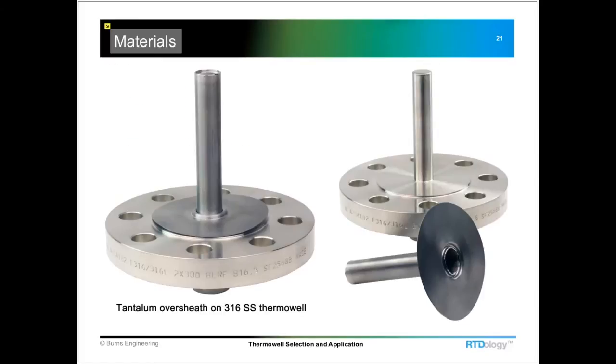One of the more common ways of handling corrosion due to acids is with a tantalum oversheath on a straight stem Thermowell. This is a rather expensive option, but it does work really well. The basic Thermowell can be 316 or 304 or really any other base material that gives you the strength required for that particular application. And then the tantalum oversheath just slips right over it and provides the corrosion resistance.